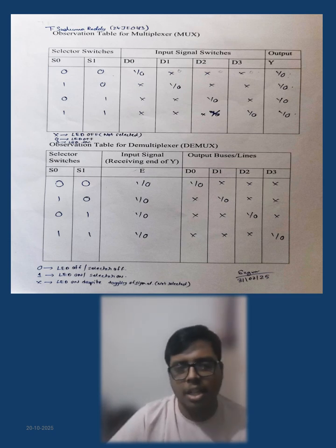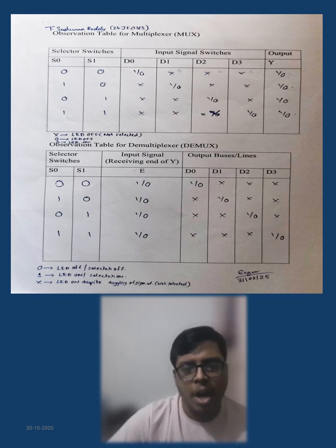To make that circuit, you will need more AND gates, more NOR gates, more NAND gates. So to minimize that, they have made such a system where they try to find some tendency or some generalization to specialization. Like if there is some trend, we can minimize the circuit. So you minimize the circuit based on the trends, that only one switch is selected and the others remain in the don't care condition.